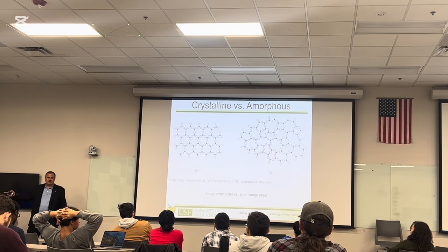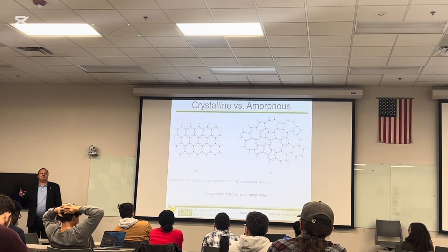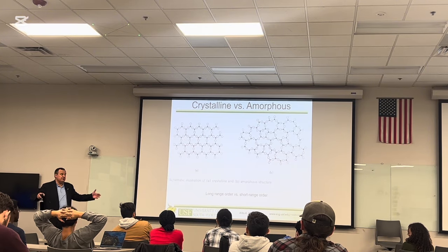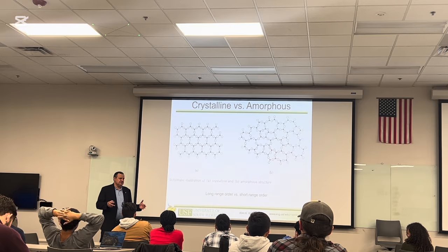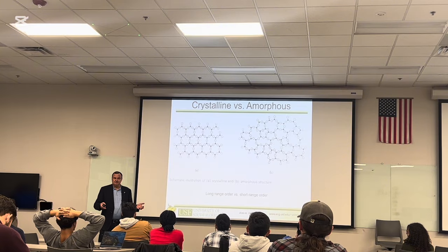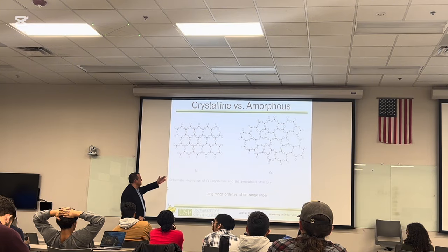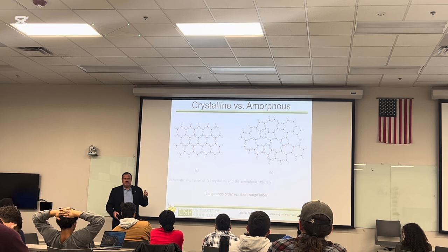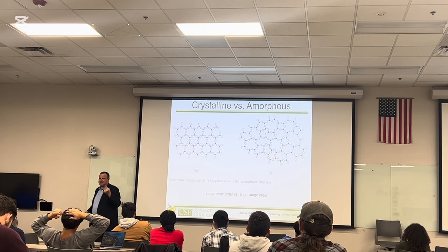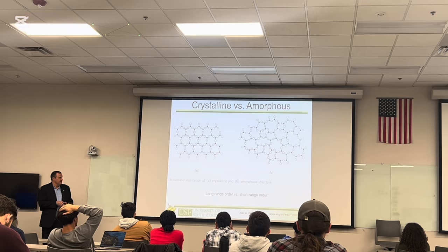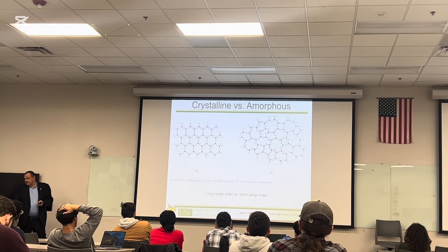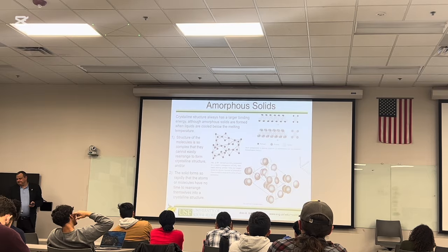And the guys mentioned crystalline versus amorphous. Crystalline, imagine a big pile of bricks that's arranged in a periodic array versus randomly distributed. Which one is going to occupy a larger volume? So what you see here on the left is quartz. It's SiO2. So the backbone of the structure is the same. It's the SiO2 tetrahedra. On the right, that's glass. So long range order versus short range order.